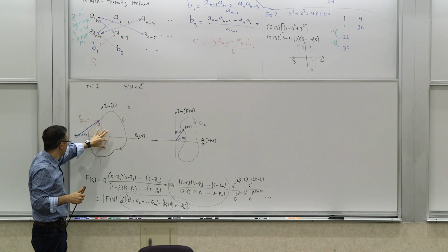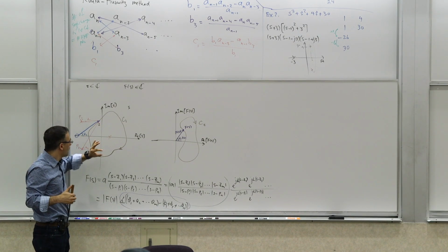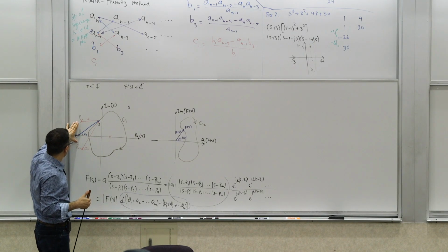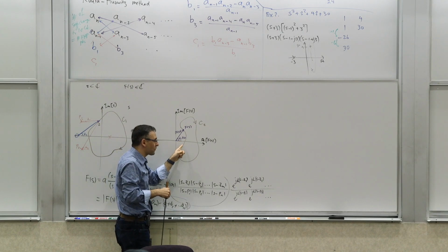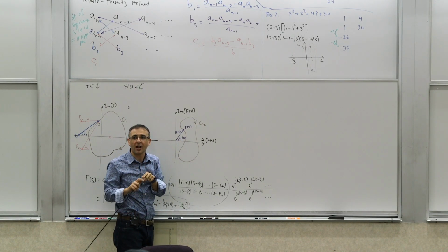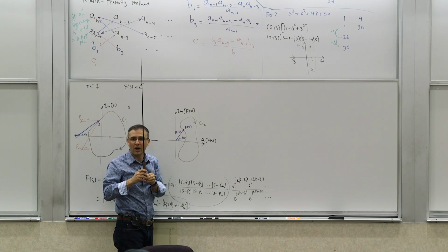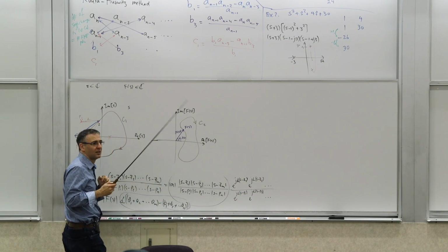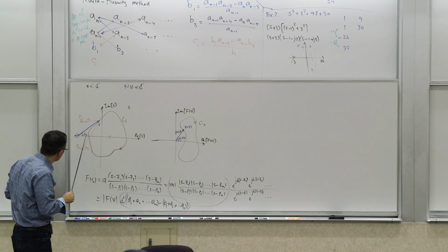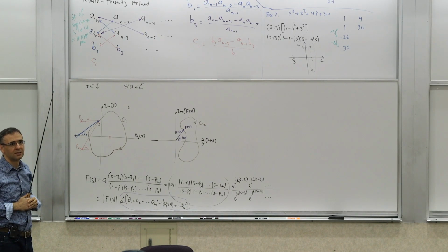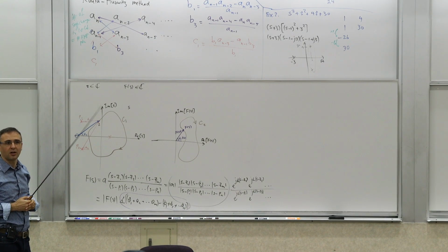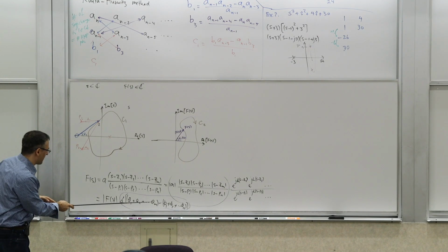And since the total phase of this thing is the sum of all these phases, these with positive sign, these with negative signs, right? So in this scenario, if this was my pole-zero constellation, I had these 3 poles and that zero, this will have to encircle the origin how many times? Once. And in what direction? Clockwise or counterclockwise? Let's say this contour is going clockwise. If this was a pole, counterclockwise, right? Because of this minus sign.